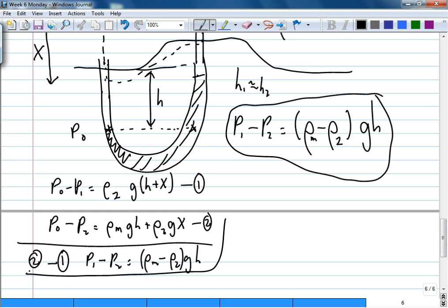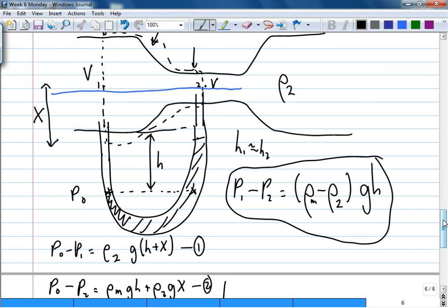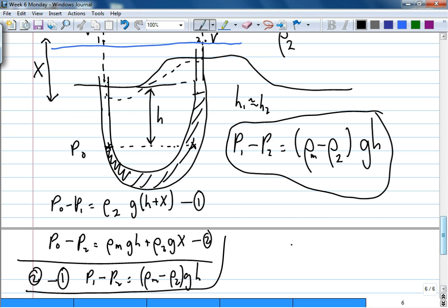So to get the flow rate, there are two unknowns, V1 and V2. I need two equations. One equation will be Bernoulli. The other equation? Conservation of mass. So two equations, two unknowns, so we should be able to solve. First equation, m dot in equals m dot out: rho A1 V1 is equal to rho A2 V2.